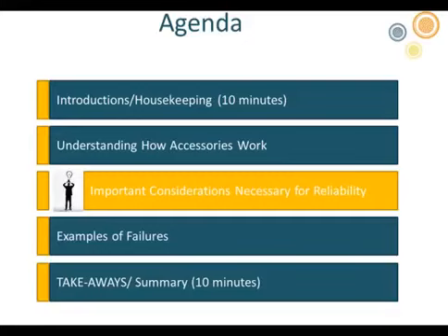Okay. Typically, we don't. It's very uncommon to see it at the base of the termination. Occasionally, you see it at the lug end of the termination, and most often that's caused by a crimp that was put into the lug that was not filed off or became a sharp edge or sharp point, and it will cut or puncture the silicone on the end and start to tear.